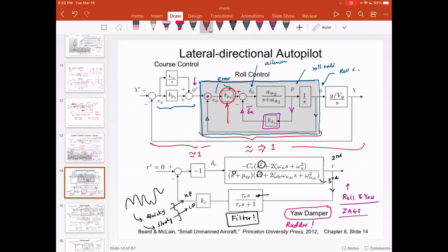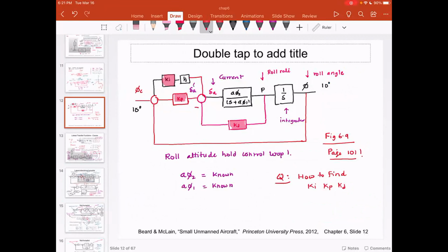Yes, so Alejandro, before you design the autopilot, you have to trim the aircraft, because this transfer function we obtained from the trimmed aircraft. Because please note, the original equations were nonlinear. We trimmed, so we linearized, and we found this transfer function.